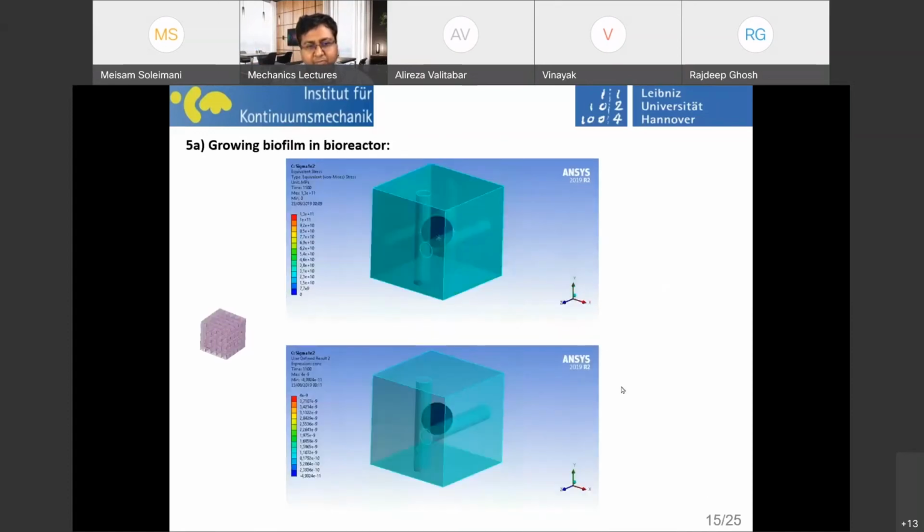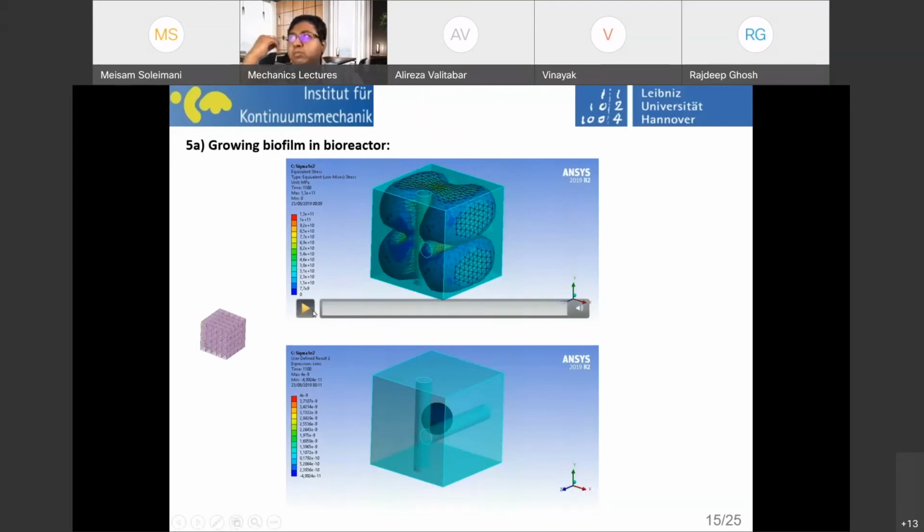But in some cases, for example this one, because the contact is very frequent, there's no way to just decrease sigma critical. If I recall correctly, the ratio of the volume change is around 40, meaning the volume increases 40 times. This little sphere just fills the available space in this very complex geometry, and a lot of stress is trapped and accumulated there. I remember that we had some surface instabilities, some surface buckling due to those things.